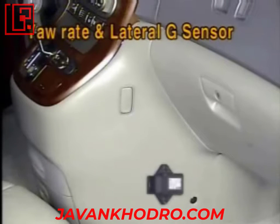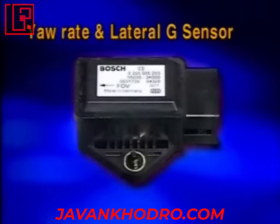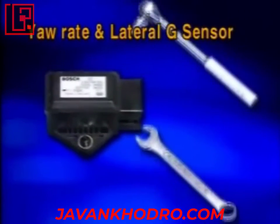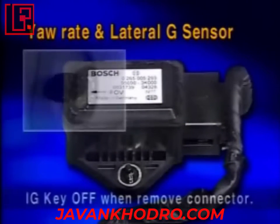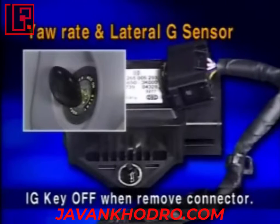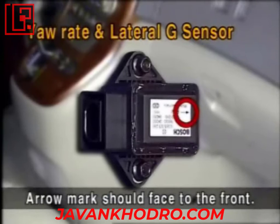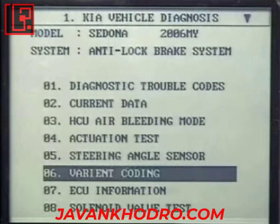The yaw rate and lateral G sensor is installed at the lower part of the center console. As the yaw rate and lateral G sensor is sensitive to shock, be careful when handling it. It should be assembled with a ratchet or spanner. When the sensor connector is removed or installed, the power should be off. Further, the arrow mark on the sensor upper portion should face the front of the vehicle. Among the diagnosis items of the scanner, there is the variant coding item.